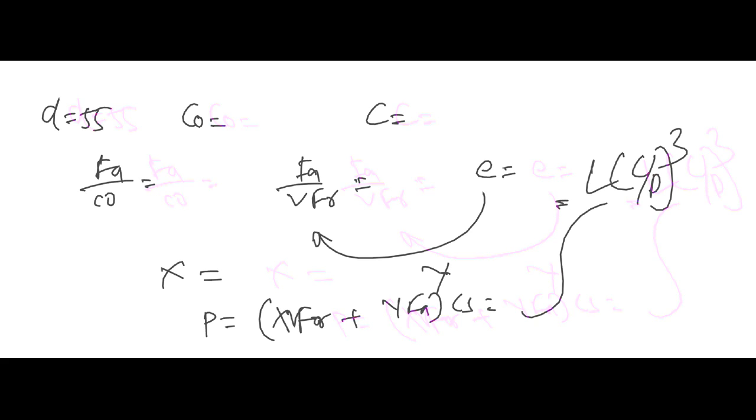Now repeat this same procedure until L calculated is greater than L required. Okay. I hope you got the idea how to find out the life of bearing based on static as well as dynamic loads.